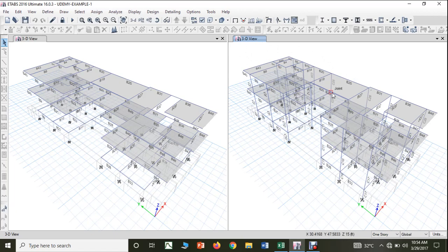Now according to this, you can see that since this is the topmost floor, the load that you are going to have on these beams is comparatively lesser compared to the first floor. And compared to the first and second, the load that the plinth beam is going to experience is again less, because the plinth beams are placed only to increase the stiffness of the column, but they will not take much of the load.